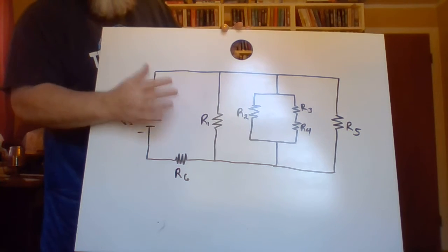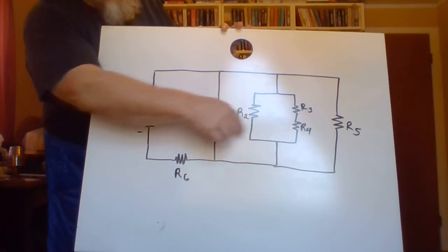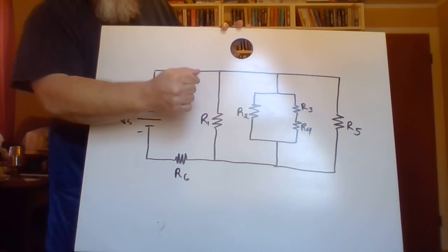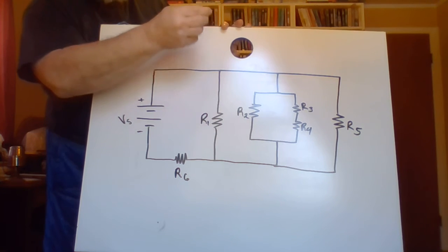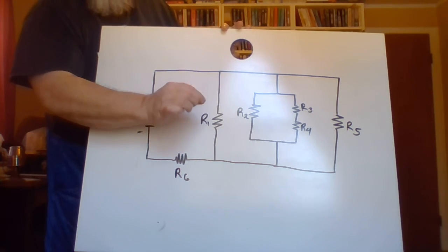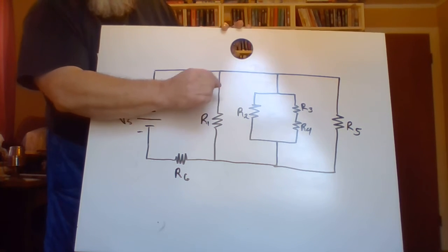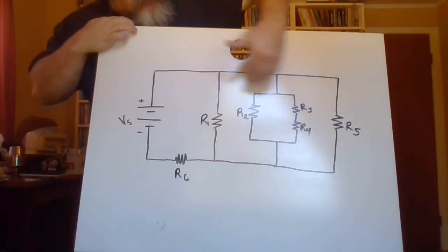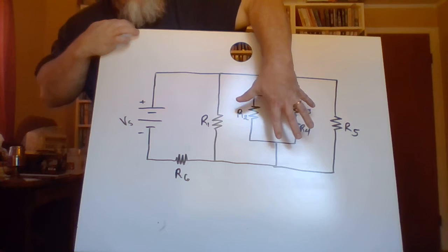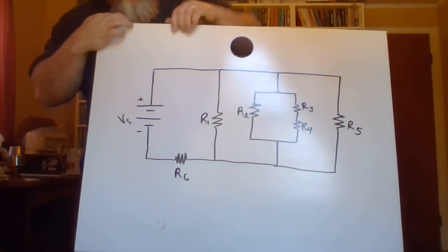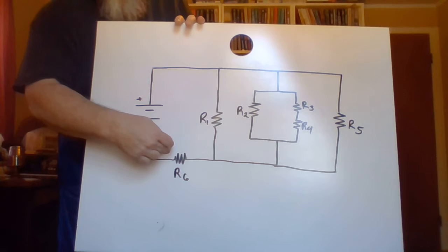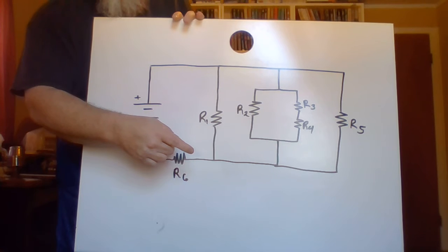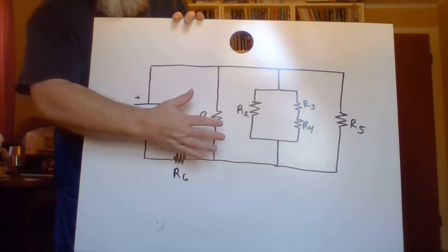So probably this grouping is not getting very much voltage because think about it, the effective resistance of resistors in parallel is always smaller than the smallest resistance in that parallel grouping. So this part of the circuit over here is going to result in a relatively small resistance. This one might be larger than that. This one might be hogging all the voltage. Okay? Going to do a different diagram and see how that changes what we're looking at.